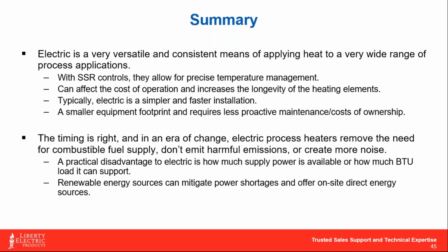As many of the controls are microprocessor based these days, I would strongly recommend having surge protection in front of those control panels. Some of these panels can easily get upwards of $40,000 or $50,000 depending on the size of that SCR controller, in which case you want to make sure that these are being protected appropriately.